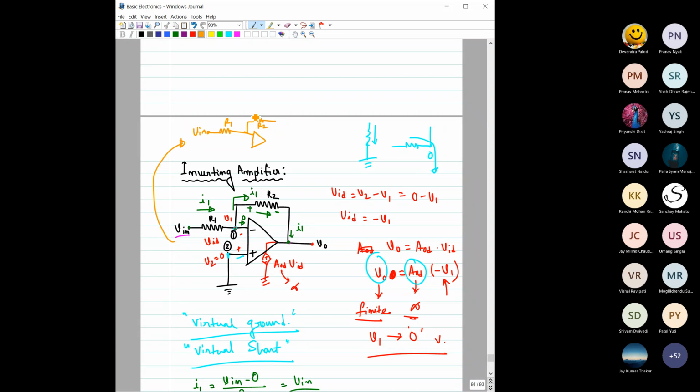Inside you have an op amp. Now the question is, can the current go inside this op amp? No, right? Because the impedance here is open, so no current can flow through this. Then whatever the current is, that entire current has to flow through this path only. There is only one path, right? It cannot go inside.